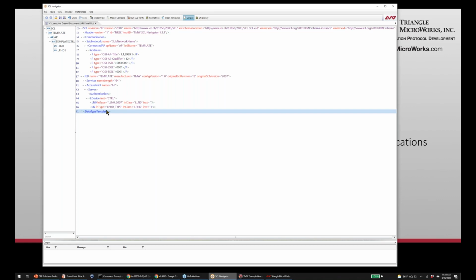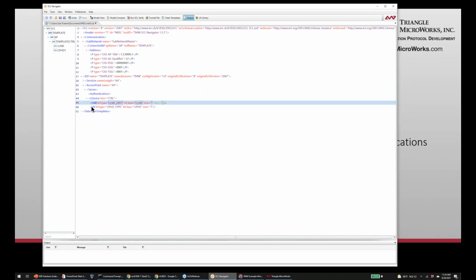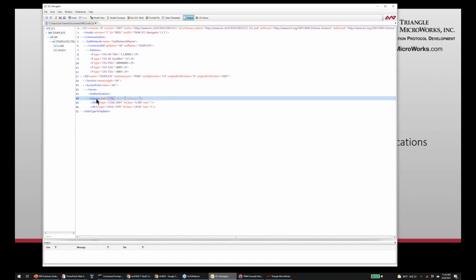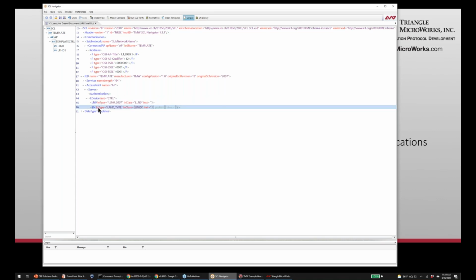These are our data structures. They're fairly arbitrary constructs to organize the data that we need in our device, but they are standardized in 7-4 and 7-3 and 7-4-20 and so on. A logical device is required to have an LN0. LN0 collects the system data for 61850, our control blocks for communications, and some other information that applies to the whole logical device. Our IED has to have one LPHD.